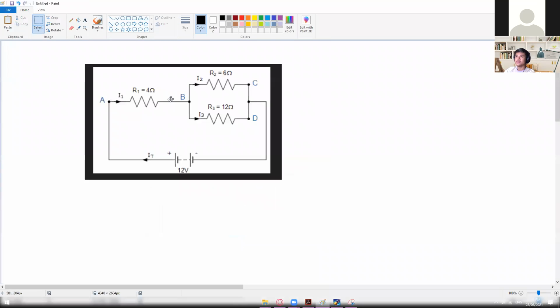Okay, so in applying KCL, that's super simple. We can actually find the KCL equation right here, since we have one current entering and two leaving. Just find the node wherein there is a current that is entering and then a current that is leaving at the same time. That's the way for you to know where to start doing your KCL equation.